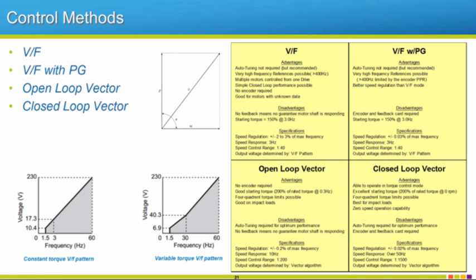You obviously want to make sure if you're going to be running a drive with your induction motor, or if you have a PM motor too, that the motor's able to handle it. Most motors nowadays are able to handle these drives because they know you're going to be running them on there, but just make sure that it's able to handle this pulse width modulation that's coming into the motor. Okay, so make sure the actual motor can handle this higher voltage that it could be seeing.